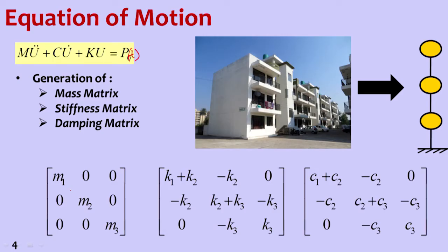In K1 plus K2, you can see there are off diagonal terms. So, we can call this coupled in stiffness and coupled along damping, while it is uncoupled along the mass matrix. In simple words, when we write these 3 equations of motion, one for each point mass, we cannot solve these equations independently.